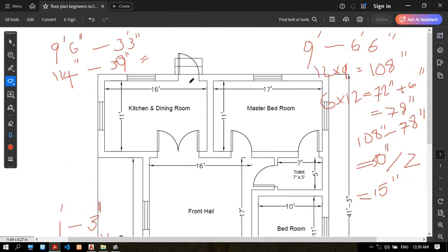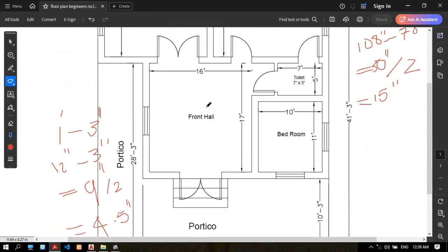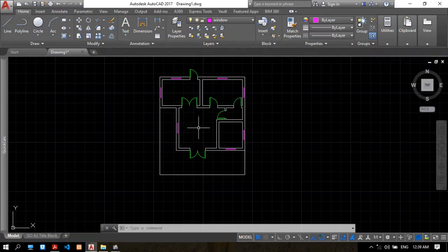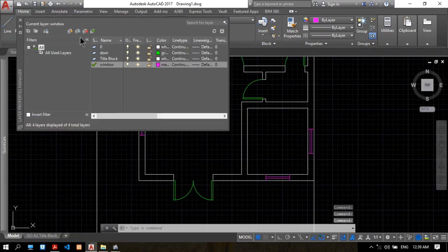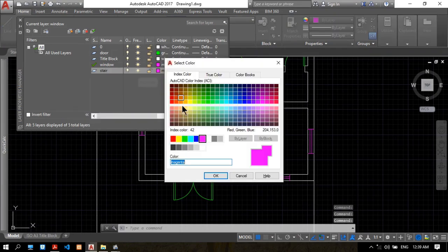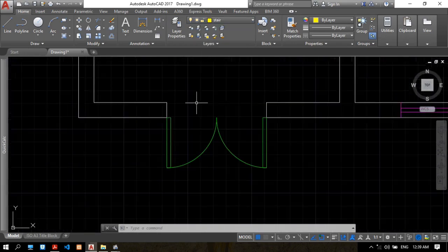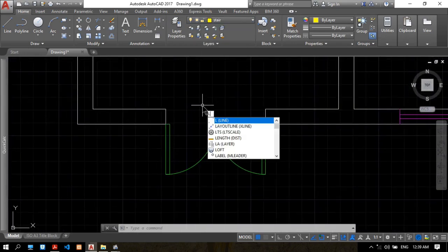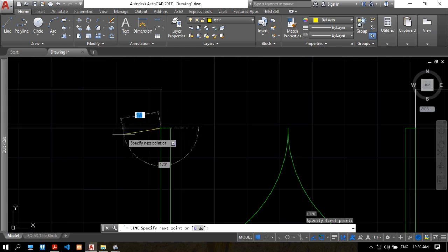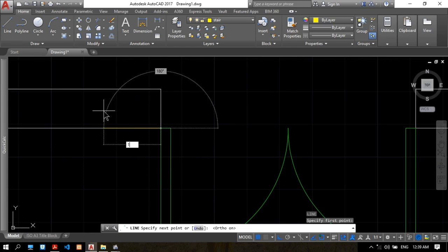the entrance and the exit from the backyard. Okay, so to make this stair here, STAIR, type stair, and choose the yellow stair one. So choose the stair here, and to make this line, use offset of 1 feet.